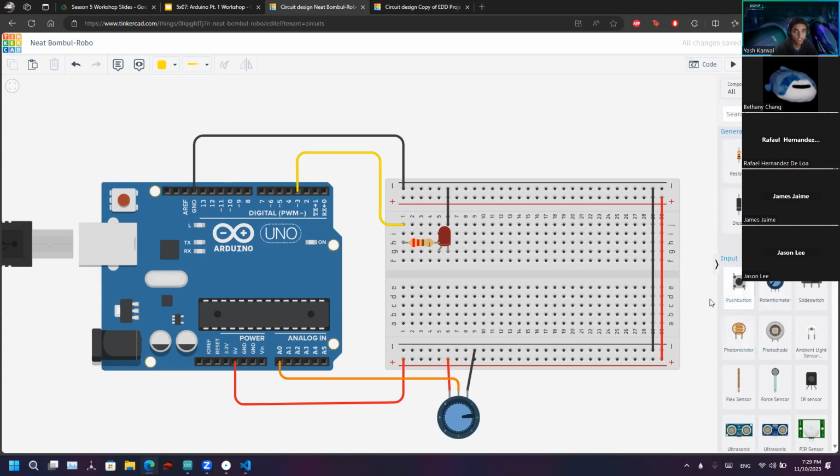So this right here, push button right here. Let's bring it out. Push buttons are kind of interesting in the way that they work. You actually have terminal 1 with 1A and 1B. They're connected together in one short circuit right here, one wire, and same with terminal 2. So if you put a signal through, let's say this right here, it'll go directly across to here. But if you press the button, it'll go to terminal 2, so it'll go on the other side of these two. So that's very useful for what we're going to do.